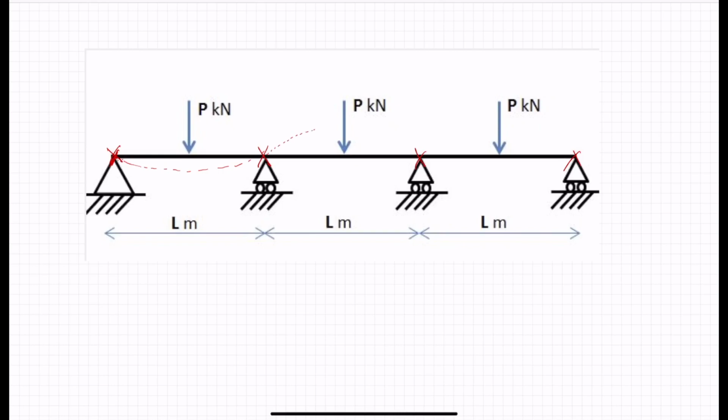if you think just to the right of the supports, the left hand force will cause the beam to rise up on the right. Similarly, we're going to have a deflection on the right, and that will want to cause the beam to go up on the left as well. Now, why is that important? It's because we've also got a force in the center as well, and obviously that will want to cause the beam to go downwards again, like this.